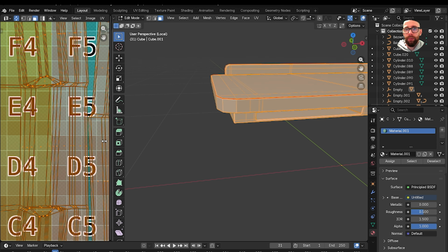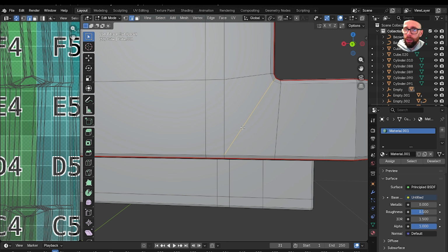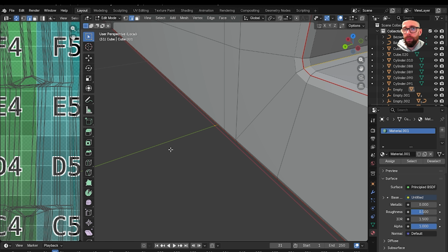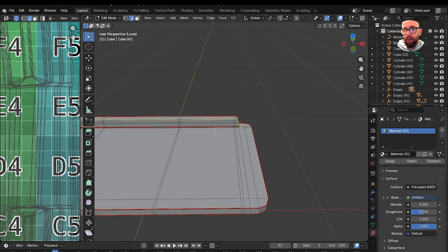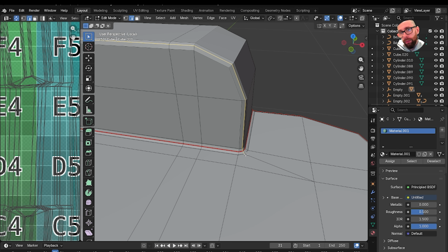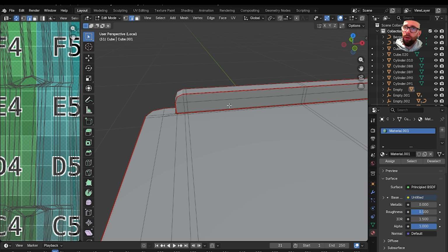We're also going to want to make sure we grab along the edges along here. We don't need that bit. So sometimes you do need to deselect as you're doing it. So I'm going to come along and grab these, mark seam like that. So this line here, again, I'm going to deselect along there. Right click and mark seam. So this one now will unfold flat.